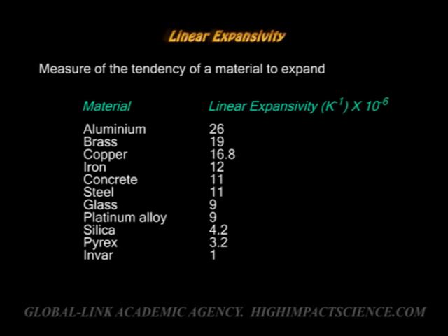When hot water is poured into a tumbler made of ordinary glass, it breaks. However, when a Pyrex tumbler is used, there is no danger of it cracking. Pyrex glass, with its low values of expansivity, will not suffer very large forces of expansion as it undergoes temperature change.